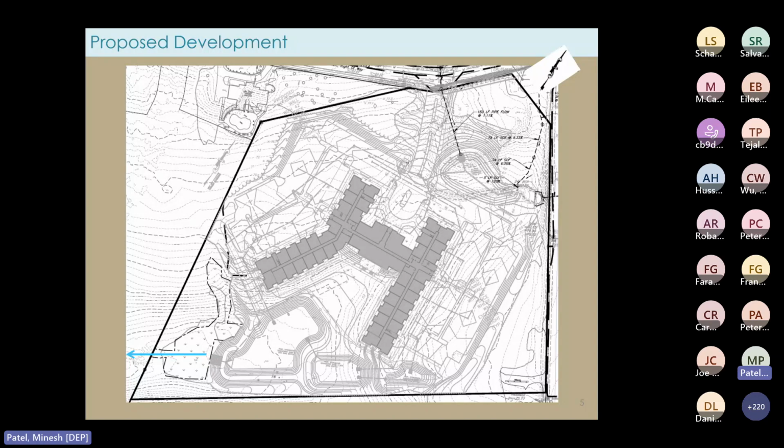From the stormwater management report, the narrative states there are 3 small-scale infiltration basins along the southern border that are designed to provide extended detention of the larger design storms, plus a northeast detention basin for the off-site runoff entering the site to the north and east. So immediately, there's a big issue with this design. All 3 of the basins proposed to meet the GI requirement are grouped together at the southern side of the project. Again, clustering these BMPs together is not compliant with the GI requirements. Remember, the BMPs have to be distributed throughout the site and manage stormwater close to its source.